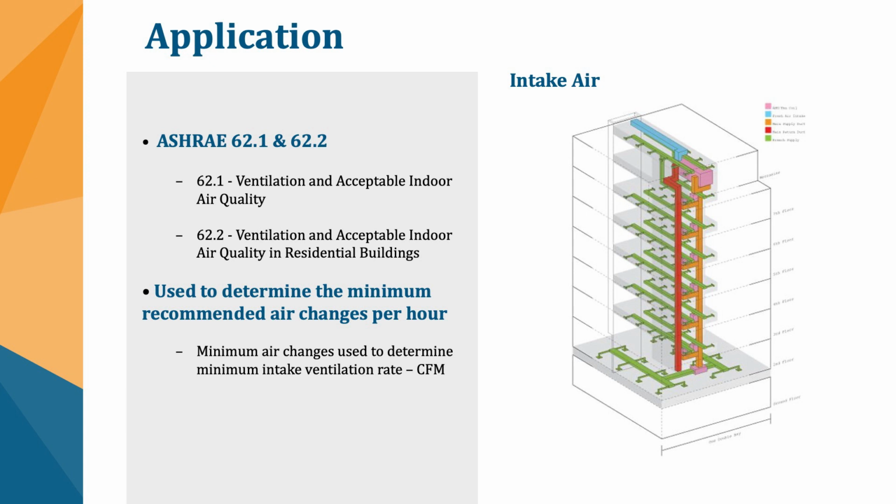Now, in order to do that efficiently, you could size your system so that the fan is basically running for a set amount of time. You've got an ideal ventilation rate for that fan setting, and you've got the duct that is connected to that fan, and you can use that to rudimentarily set up the overall CFM you expect based on the ideal amount of airflow through that fan operating at normal performance loads.